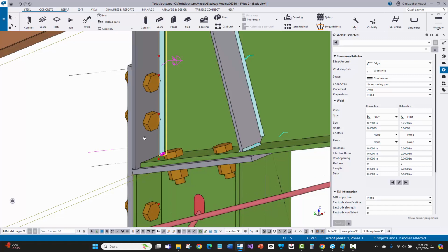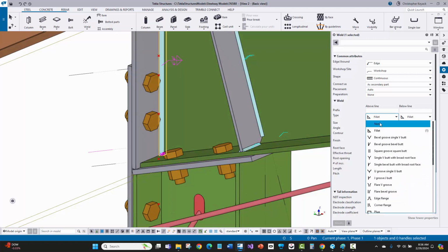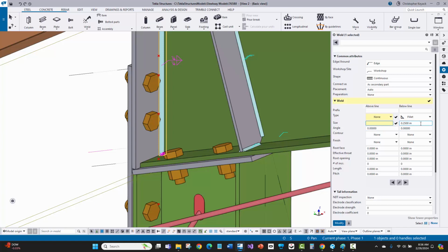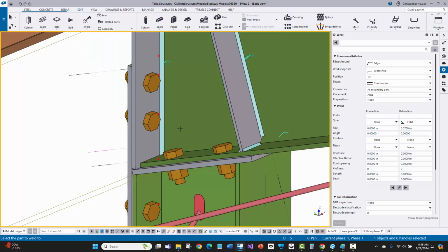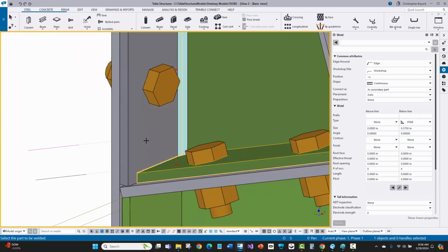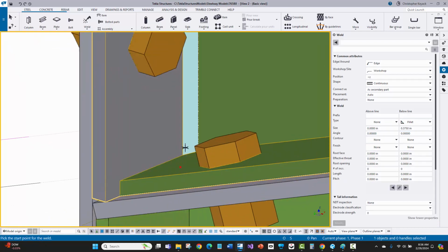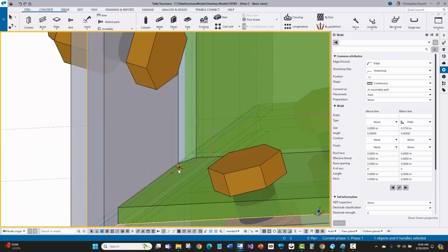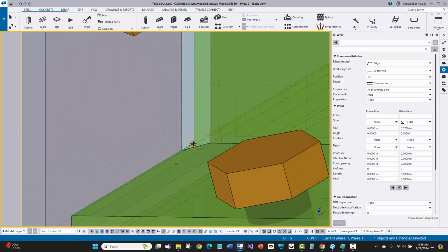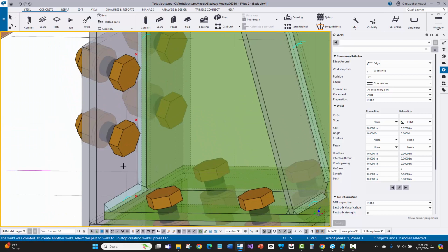All right, then it looks like I've got a 3/8 weld that's single-sided. So let's just get rid of those, and we'll say 0.375 for that size there. What we'll do next is come back into the create polygon weld command. We'll see that those settings have stuck. Again, I'll pick the beam, then I'll pick my end plates. And now I need to actually see inside of that weld to find that corner point. If I just rotate, you'll see that there's that inside corner there. So I'll pick there to the outside, middle mouse button, and then there's my weld.